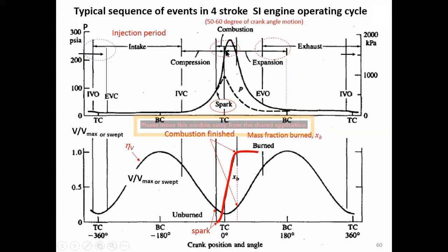Right? So from here to here, the piston is moving down and down and down. The combustion finishes around here, no more. Right? The piston keeps moving down, and the pressure is reduced because the volume increased until this point. Just before the piston moves down to the bottom dead center, the exhaust valve opens. The exhaust valve opens. Okay, by the way, the compression finished when the piston is at the top dead center.